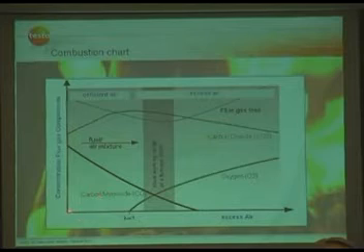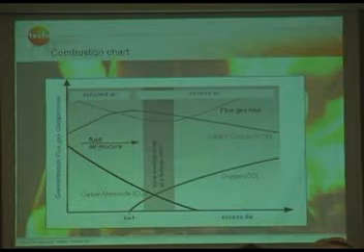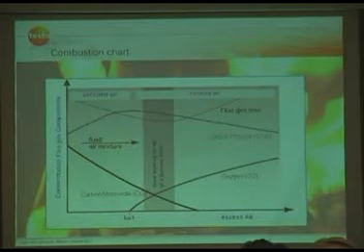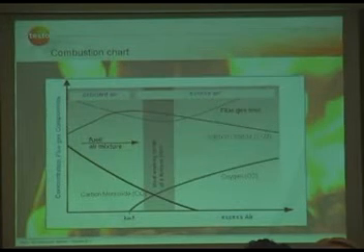As soon as you start putting oxygen into the combustion process, it starts burning the CO, and at one point there is just enough oxygen present to burn all the CO, and then at this point you will have almost the highest CO2 reading because the CO reacts with the oxygen and CO2 will be the result. This is the point where lambda is 1.